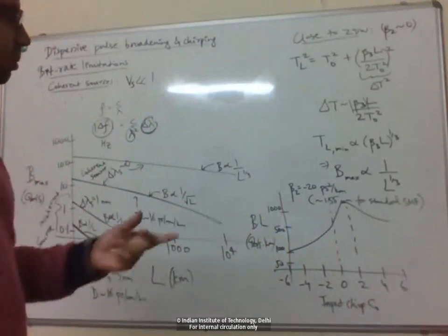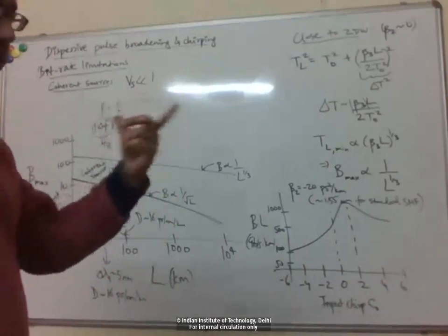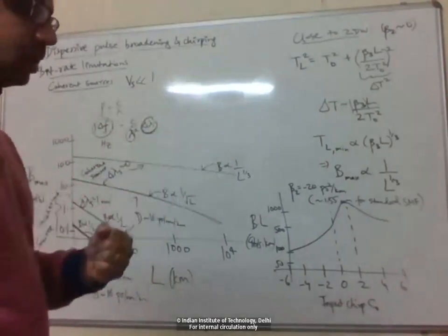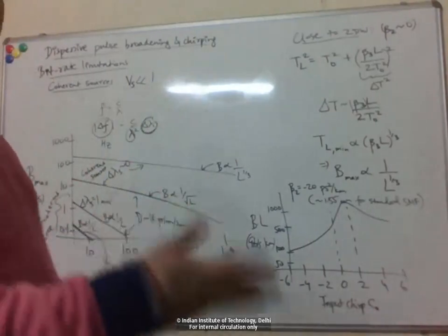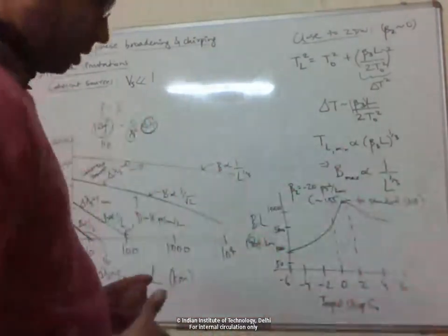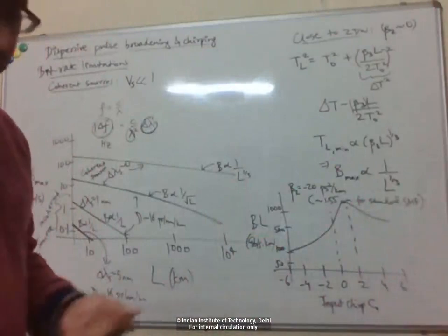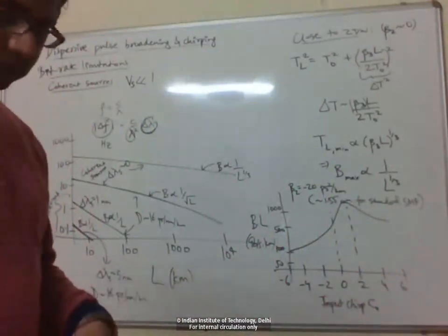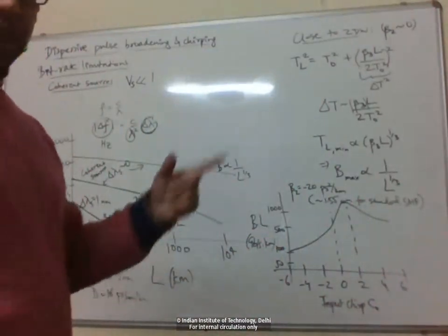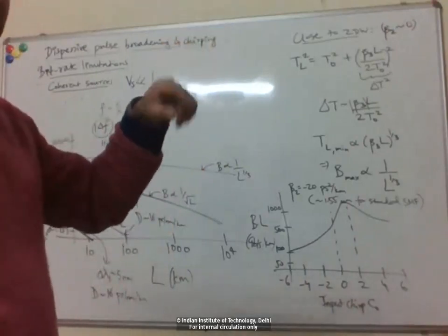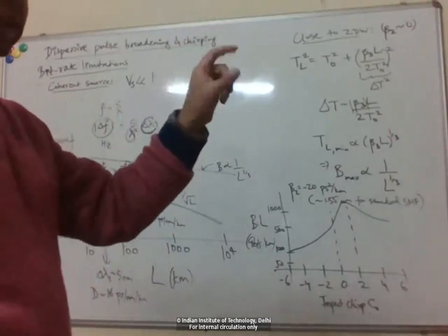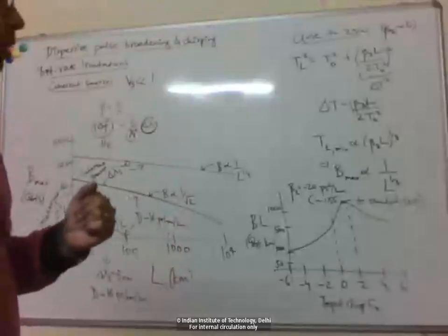That will give me a second order effect, which is beta 2 times L, and a third order effect, which is beta 3 times L. Now, if I have another fiber after that with the opposite signs of beta 2 and beta 3, then the phase will be the opposite, for beta 3 also.